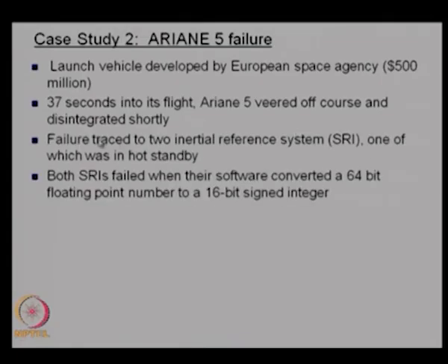Again, the failure was traced to 2 inertial reference systems, one of which was in hot standby. We learned about the standby system, which is basically a fault tolerant system. So, there were 2 inertial reference systems, one of which was in hot standby. Even if one fails, the other one can be used to get the output from the system and find out the location of the vehicle.